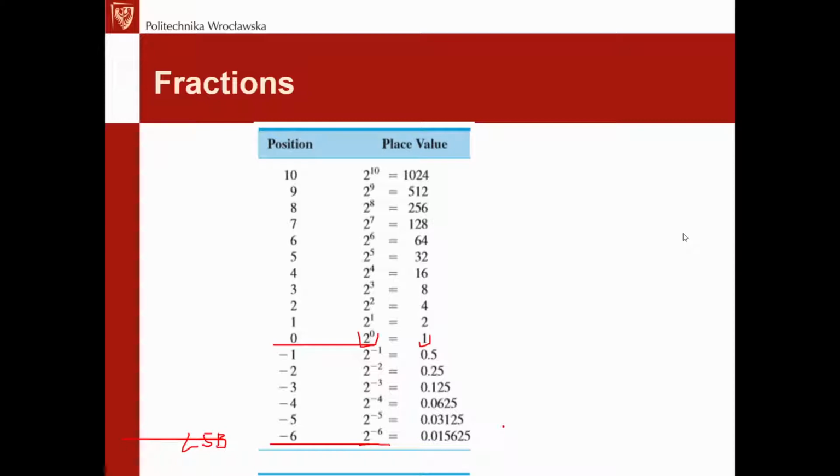Yeah, these are so-called fixed point numbers, fixed point fractions. Fixed point means that we have the weight of 1 at a fixed position. But fixed position here doesn't mean that it's always and everywhere. The fixed position really depends on our personal application, because in one application the fixed position may be at position 6, like it is here.